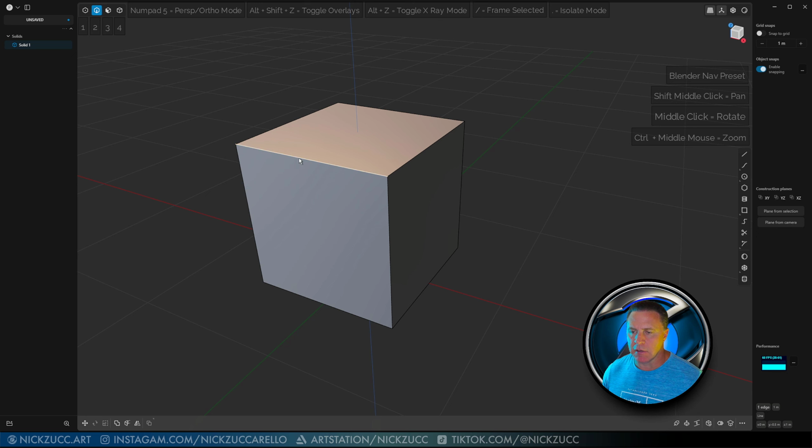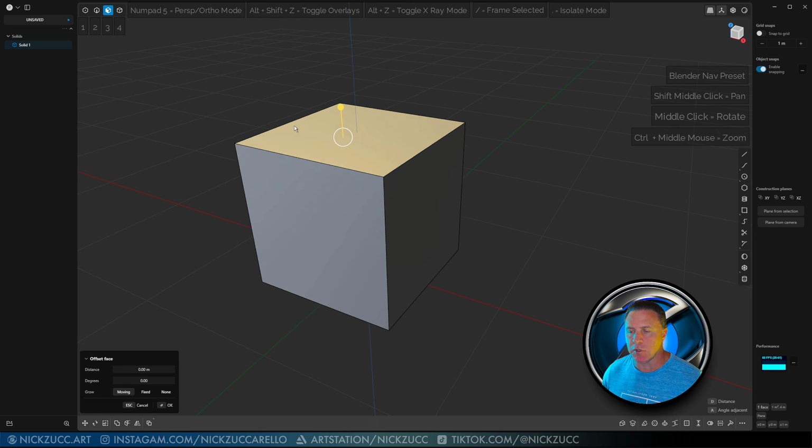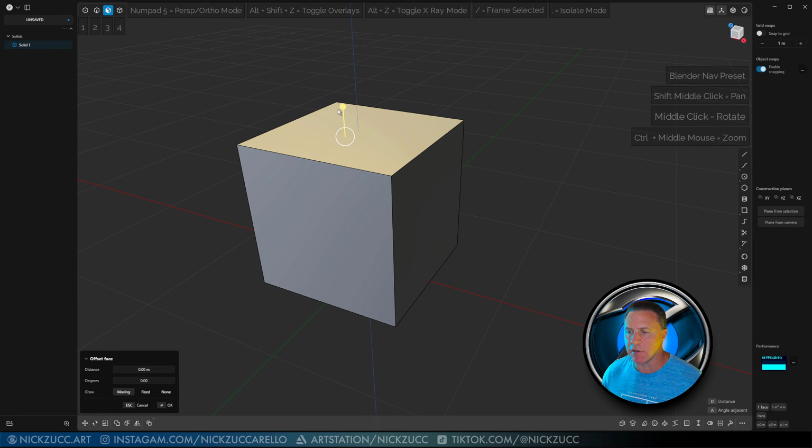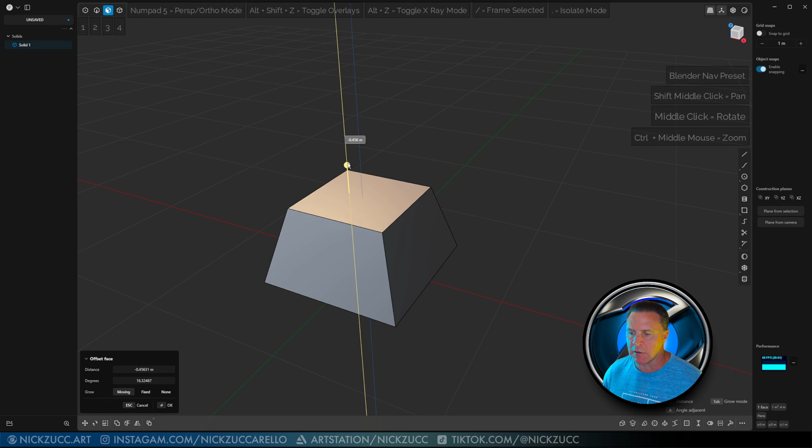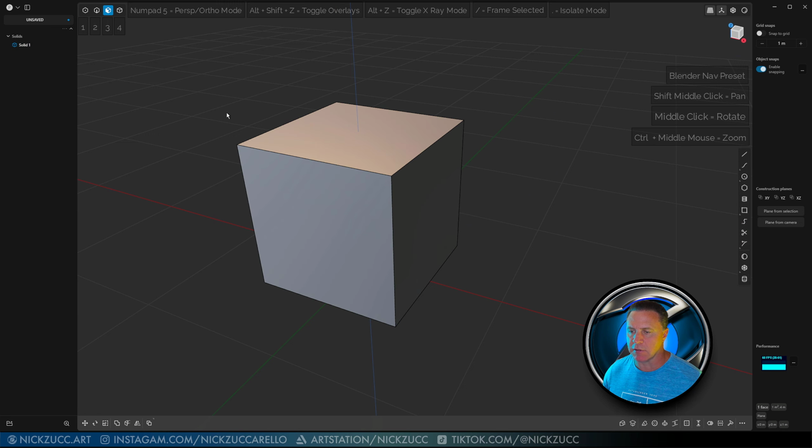Okay, so I'm going to hit escape, undo that, and if you tap 3, you're going to be able to select your faces that you have on here, and then that's going to give you like an extrude function immediately. If I select that again, this is going to give us the ability to taper and do this move function that we've got here. And 4 is selecting the whole entire object, which is called bodies or solids within the program.